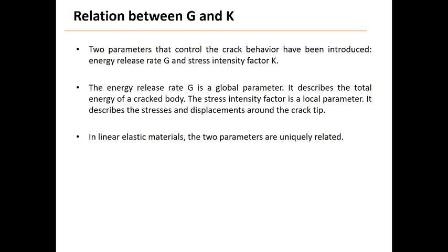This is a local analysis that allows us to look at, so to speak, more details around the crack tip. And both of them are equally true, right? So we're invoking two different principles. This is the balance of energy, conservation of energy principle, and the stress intensity factor is an application of Newton's second law, which is just the equilibrium of the stresses and the deformation of the material around the crack tip. So they are both very commonly used.